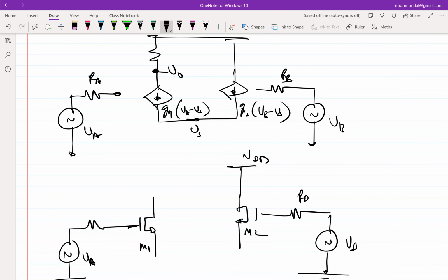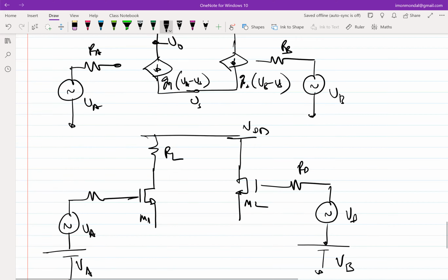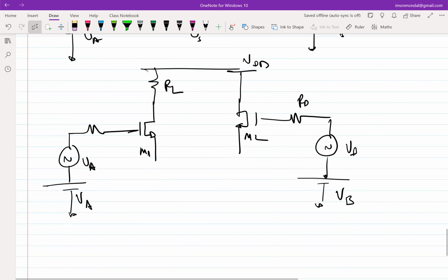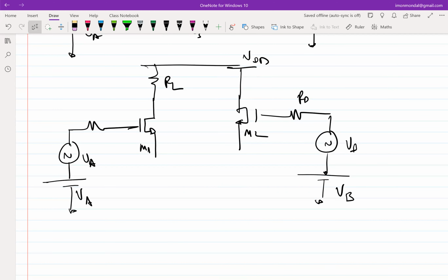M1 was kind of acting like a common source amplifier, right? Well, it's not exactly a common source amplifier, but we are trying to drive the source of M1 through M2 while the resistor was connected at the drain, and incrementally shorted on the other side. In other words, the resistor was connected to VDD. This is all good. Then how were we biasing this M1? With the current source at the source, right? So M1 was getting biased with the current source at the source.